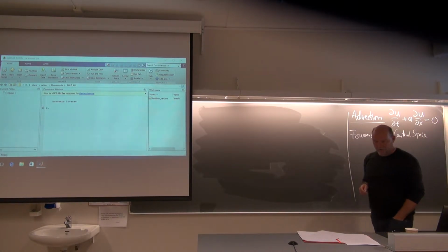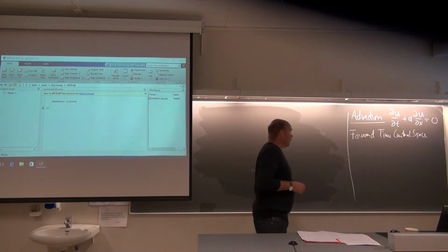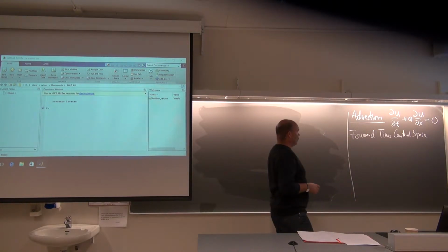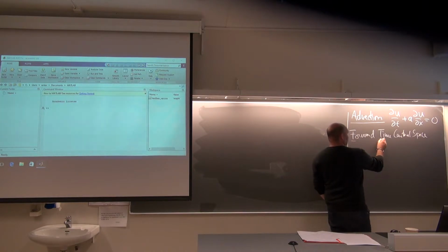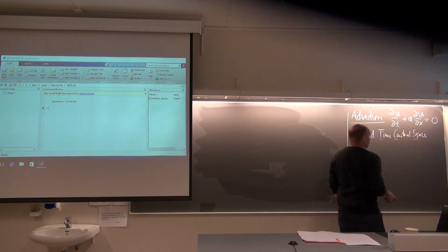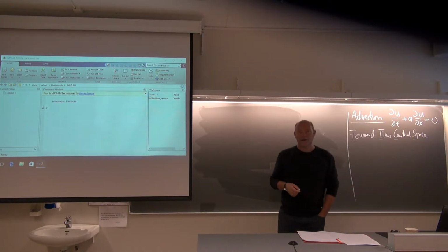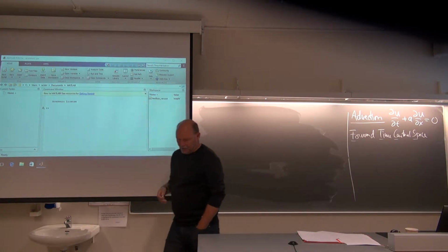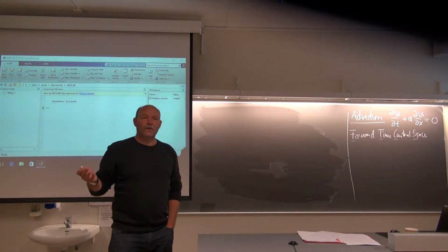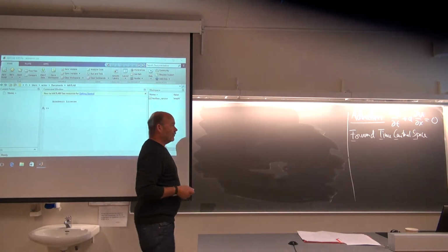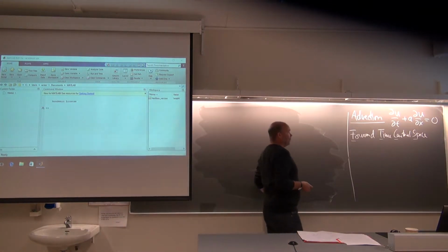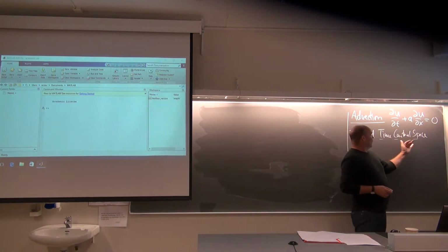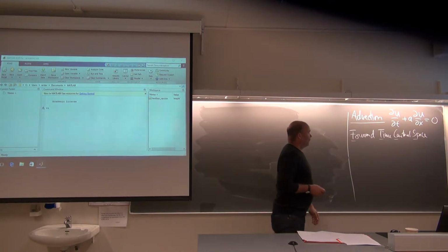Forward time, central space numerical schemes, you call them FTCS schemes. They are widely popular, typically the first one you will try, it's very easy. Forward in time meaning a first order Euler scheme, central in space meaning second order accurate discretization. So very, very easy indeed.